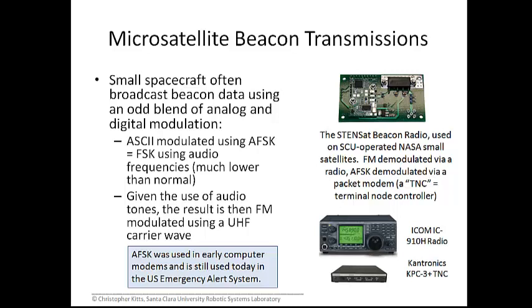So the top board there is a transmitter, and the equipment on the bottom, although it can be used for both transmit and receive, we use it as a set of receive equipment. So this particular system is a bit of an oddball. It uses FM modulation, and it does that on a UHF carrier wave.